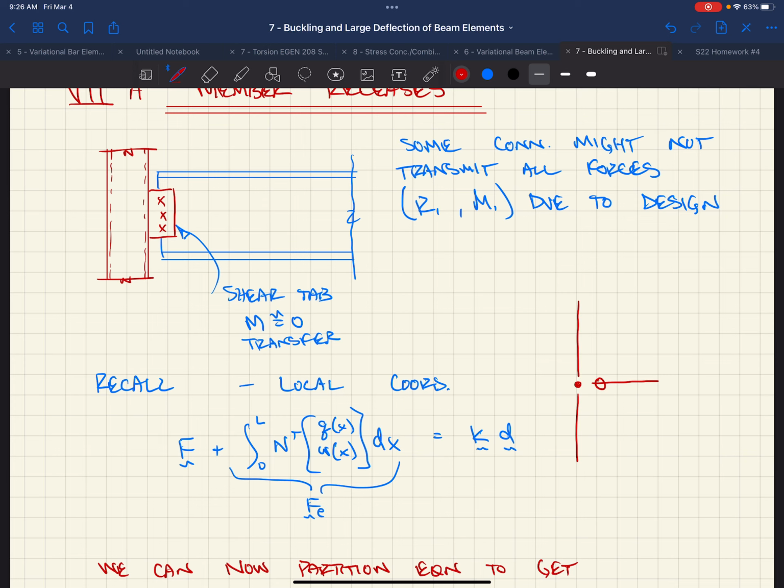Yes. If you actually did design that as fixed, why don't they just design the whole thing as if it's fixed? Because then you definitely better make sure that it is fixed, and then it starts screwing up what's going on with the columns. And it's just a lot more bolts and stuff. Yeah, it's a lot more from a cost perspective to implement that sort of design too. But you have to design for the amount of moment that's being transferred into that column. At that point, you're saying there's no moment transferred. Yeah, you assume it's zero, but the service loads are transferred.